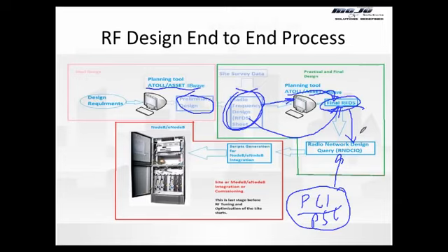What RFDS is basically, the main purpose of RFDS is to communicate with the site construction engineer how to build the site, what kind of Node B will be there, and what the tower height will be, and all those details. Using this RFDS, we communicate all the information about site construction and installation to the construction team or installation team or site integration engineer.